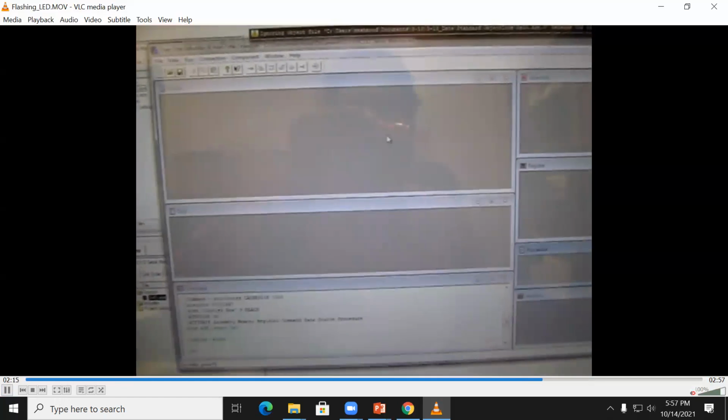Every device needs some time to turn on and some time to turn off, right? As you will see right now, because I'm going to do it very fast, the LED is on all the time. You can see flashing, but it looks like it's on all the time. You put 5 volts for a short period, then remove it, then put 5 volts, remove it very quickly. You keep the 5 volts just for one millisecond, right? So you will see it as on all the time.